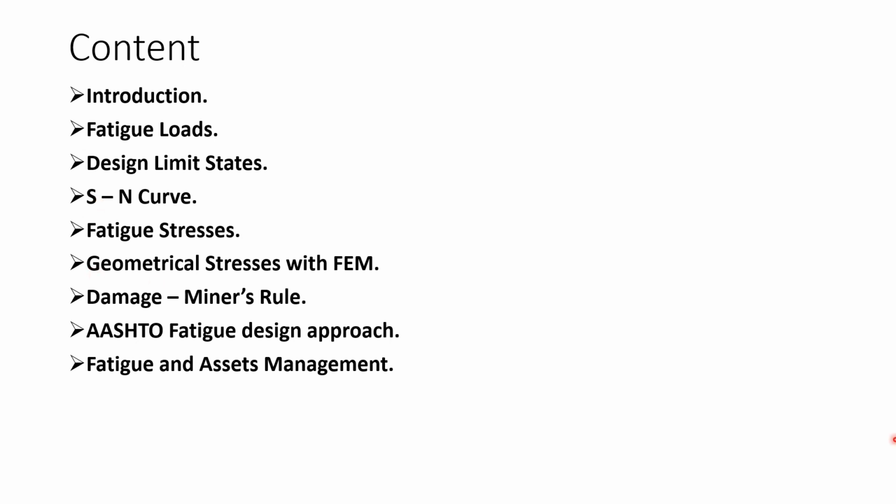In the context of fatigue stresses, we have a separate section that talks about a specific type of stresses, which is the geometrical stresses, and how we use finite element modeling to extract these stresses for the purpose of design. And then comes the section which handles the damage concept and how to use Miner's rule to plot the accumulative damage under variable amplitude cyclic loading.